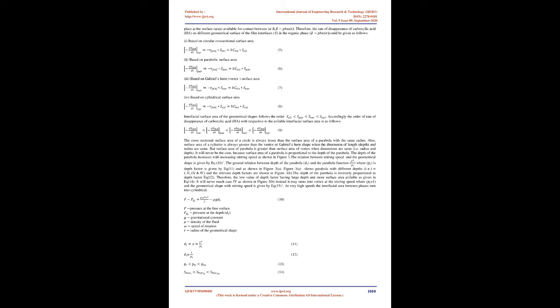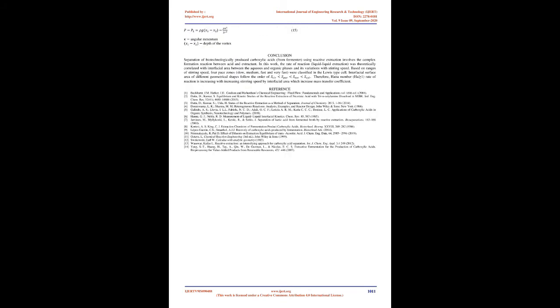Owing to the advancements in recombinant technology, we can produce almost every carboxylic acid through the bio route. However, recovery of carboxylic acids from fermentation broth is incredibly challenging. There are different methods being used to recover carboxylic acids from fermentation broth. Conventionally, the salt precipitation method is in practice. Recently, chromatographic methods, ion exchange and adsorption, distillation, extraction, and membrane separations, and so forth, have been reported for separation of carboxylic acids from the fermenter. Some of these methods are energy intensive, few are still at R&D stage and mostly uneconomical. Among all these recovery technologies, extraction, reactive extraction, is reported as a promising and viable method.